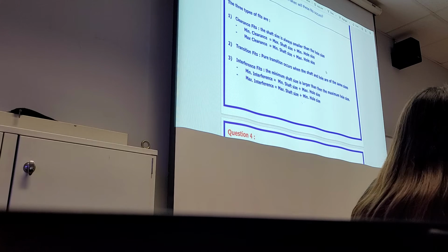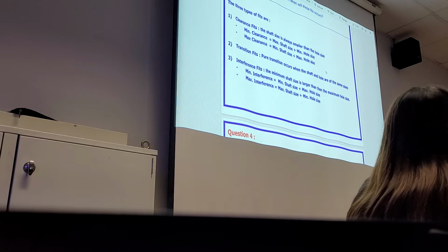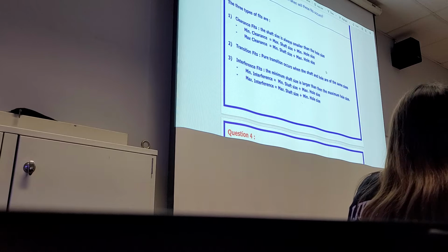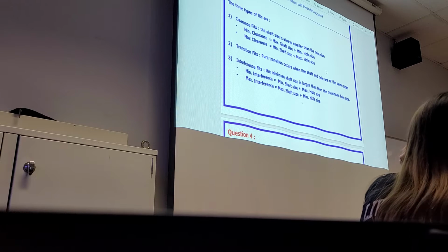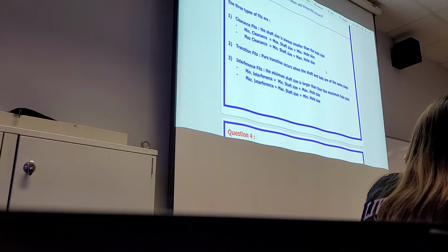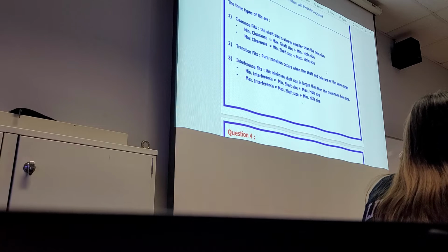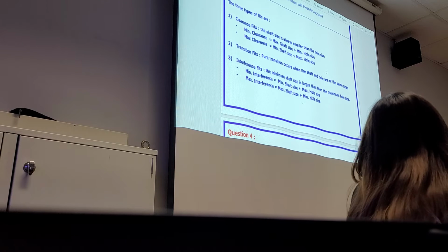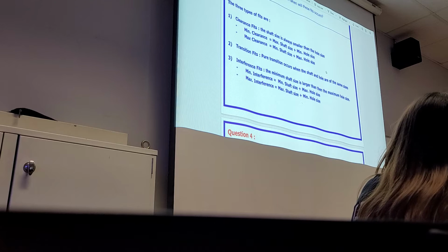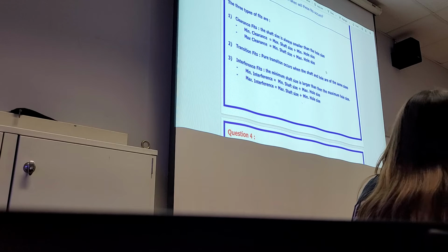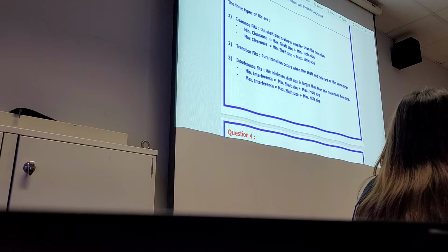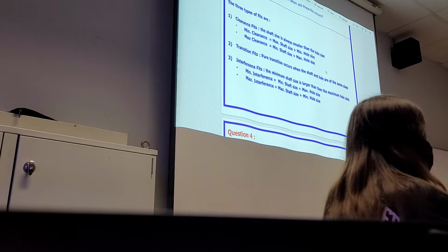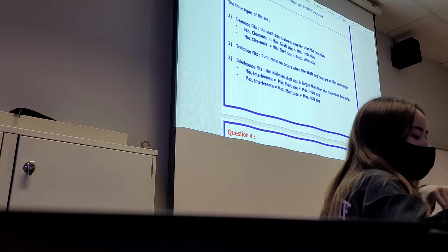When you do the calculations, it's always the hole minus the shaft. So don't use the other formula. For example, maximum clearance is basically the hole at maximum minus the shaft at minimum. When you want to find the minimum clearance, the hole at minimum size minus the shaft at maximum size. Later I will show you one example.